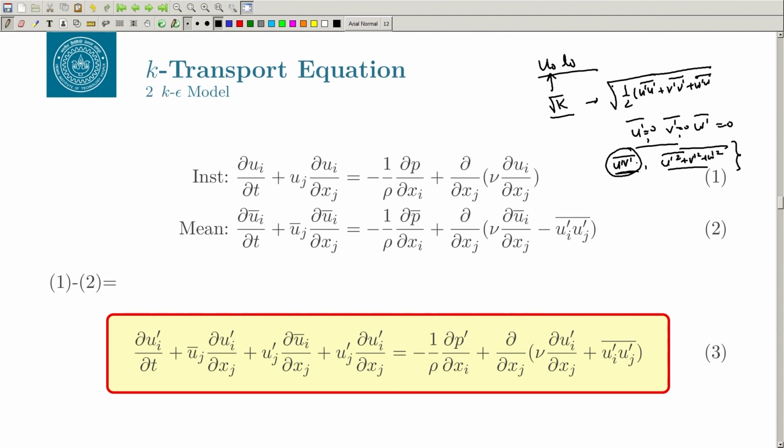So, you can get the turbulence kinetic energy, you can get the stresses, but not the individual fluctuations. If you are doing LES or DNS, you do not solve the mean flow equation, but you solve the exact Navier-Stokes equation. In those cases, you get fluctuations. Of course, in those cases also, if you take the mean of those fluctuations, you are going to get 0, right? Because that is the property of the flow.